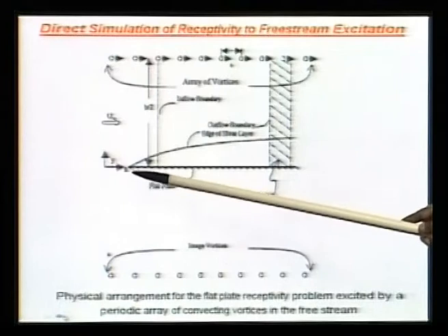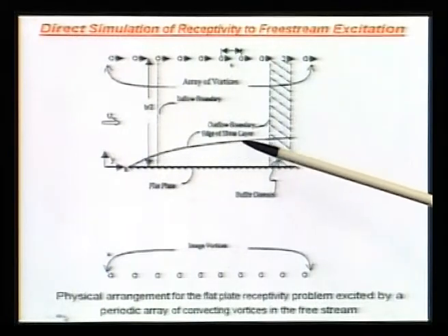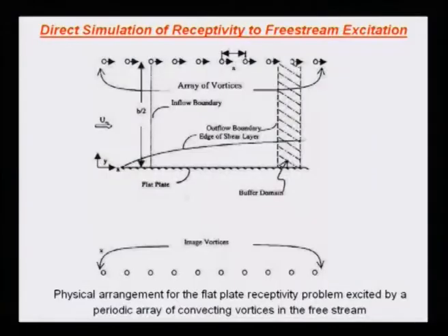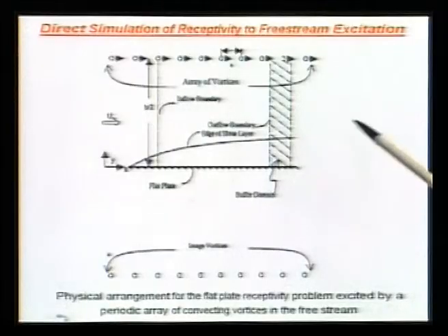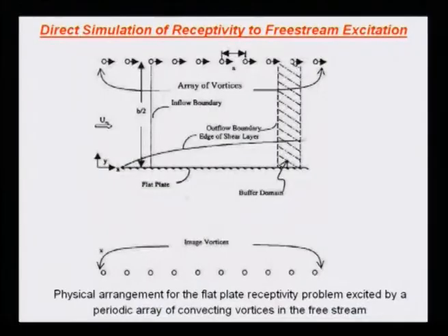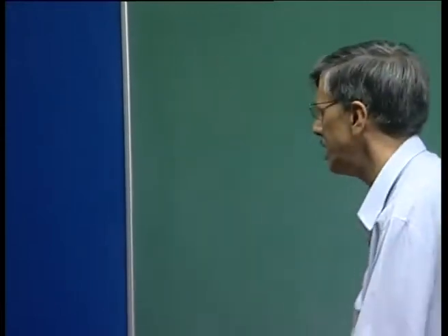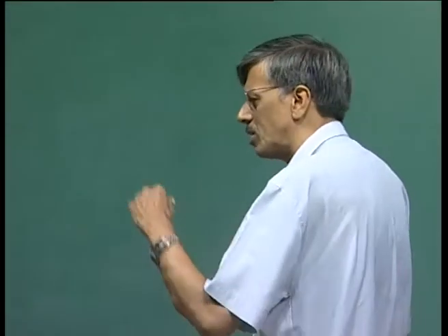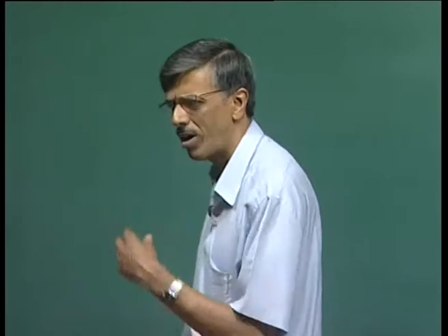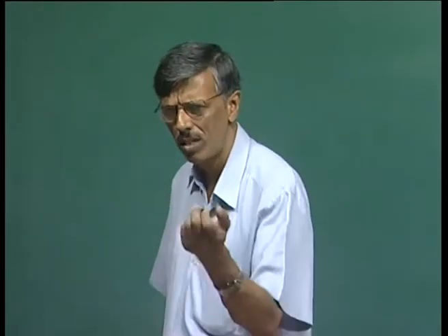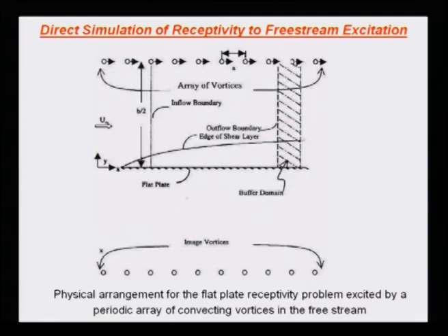The boundary layer grows from zero thickness all the way downstream, which, as the Reynolds number increases, does not completely saturate, but the growth can be neglected. And that's where we used our linear theory with parallel flow approximation.